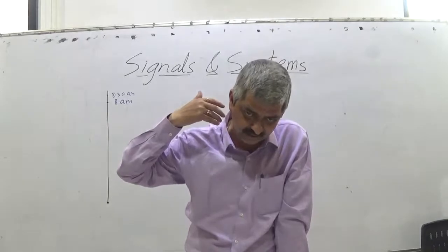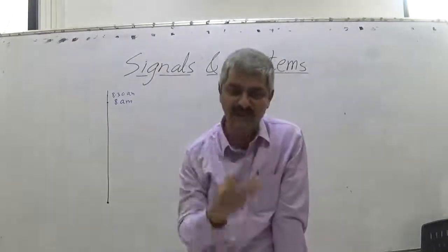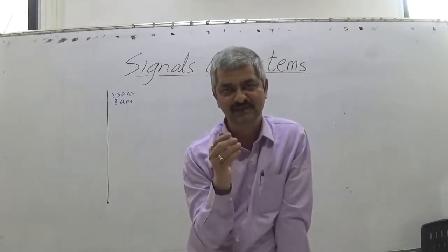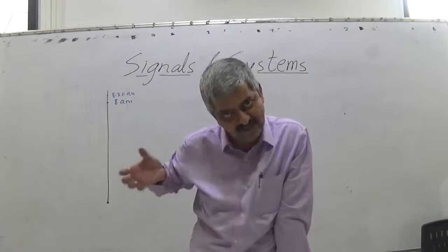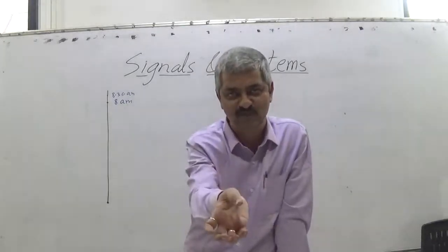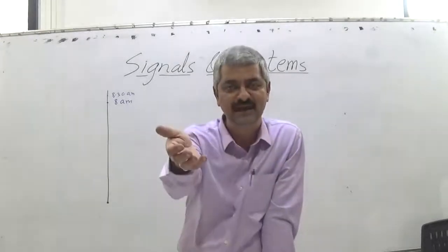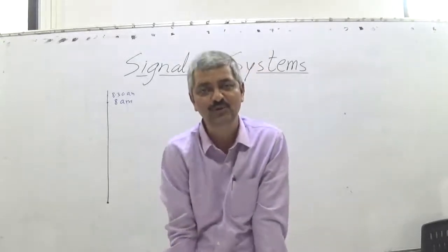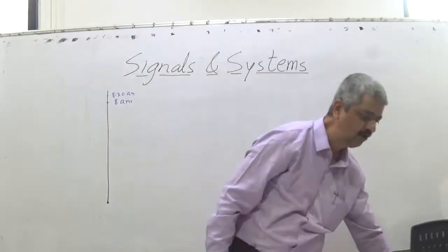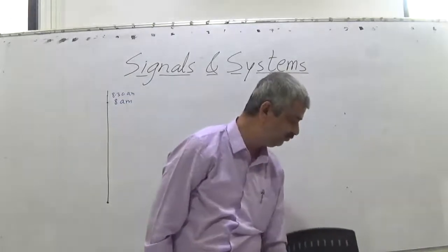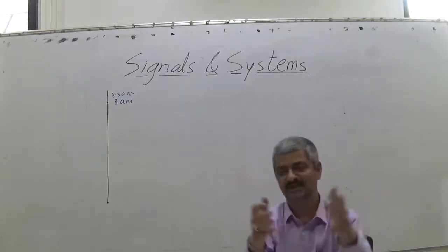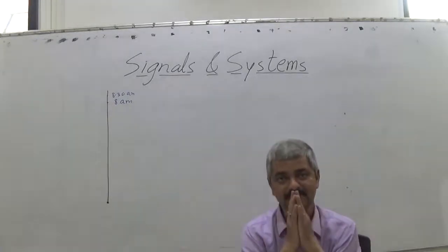In the conventional analog amplifier system, at the mic the pressure signal is converted into resistance, that is supplied by a power supply and gets converted into an electrical signal. That is amplified using a transistorized op-amp based amplifier, and that goes to the speaker, again converted to a pressure signal. So a happening of any parameter was converted into an electrical thing, processed, and reconverted to that physical phenomenon back. That was in the case of continuous systems.